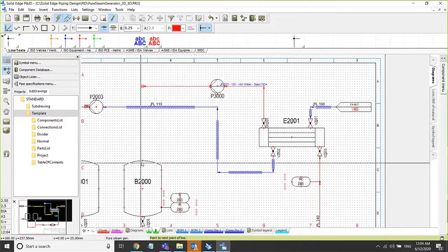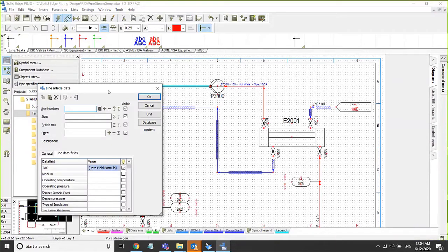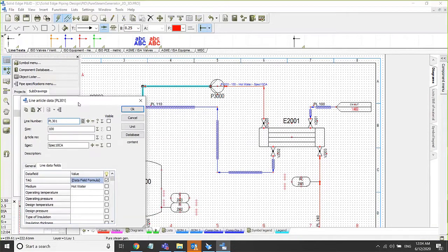to the vessel here, and edit the line, and use the copied information from the other pipeline, and we can also paste that same information, as I'm going to define a 100 diameter size for the other side. And you have the option to quickly increase the line number by one. It is easy to again place a unique name to each object on your piping schematics. Let me continue and place this information.